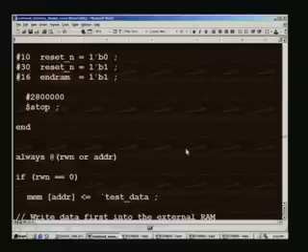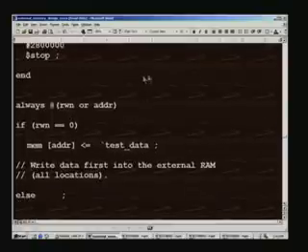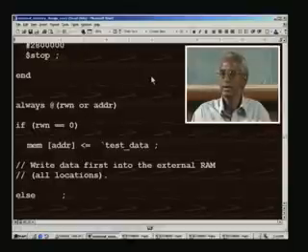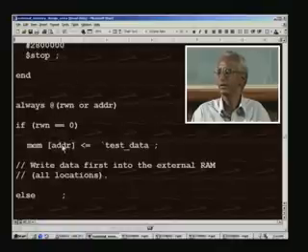Although we have written an elaborate test bench like this in order to write a particular data pattern, namely all 5s, to all the 64,000 locations at one time, then in the next phase we will change over to the read mode and check that all the 5s are intact, and that is what the test is. The result of this test should be indicated as a go no go test. That is to say, only whether the test has passed or failed must be reported, and no unnecessary locations or addresses reported.